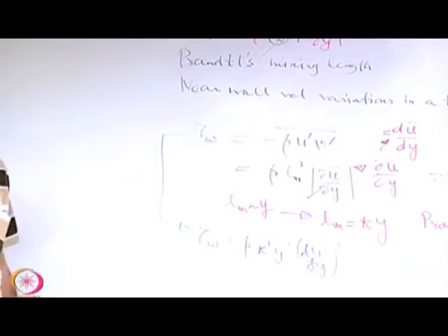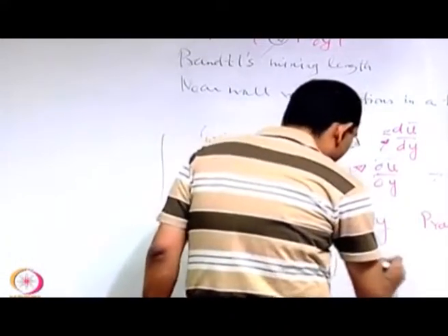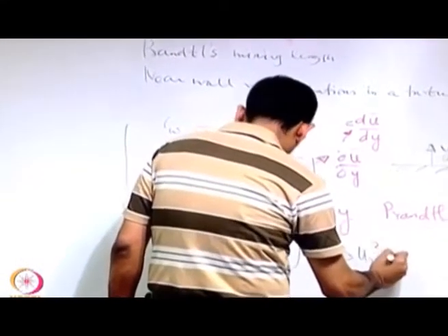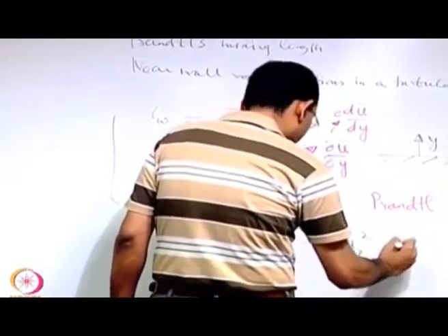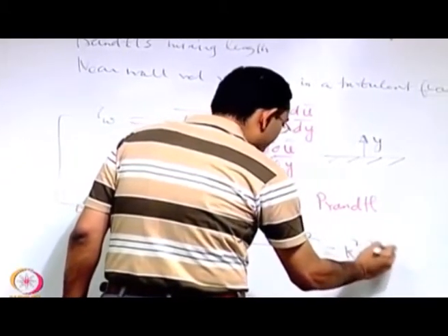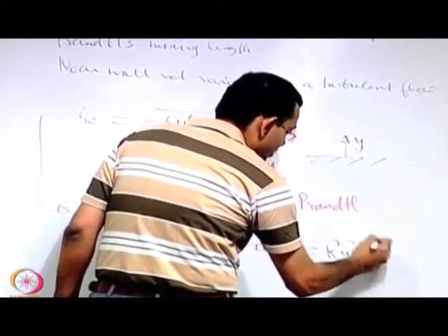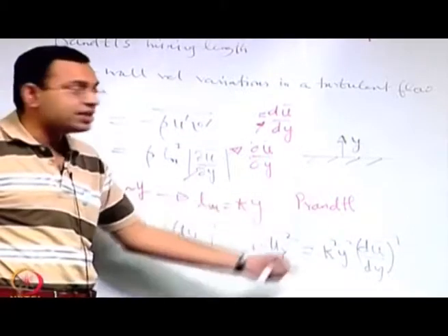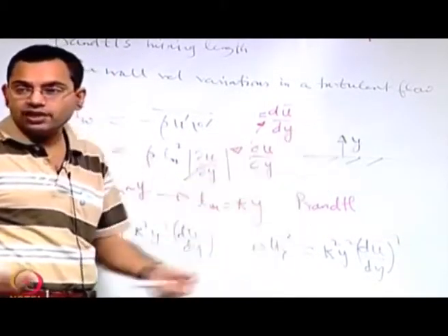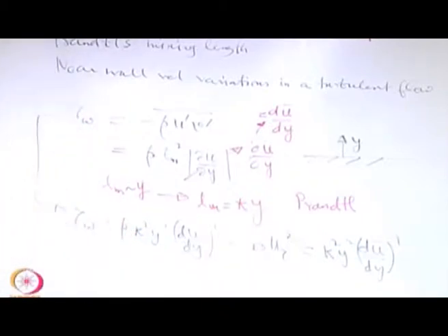What is the velocity scale, square of the velocity scale close to the wall. So that means you have u tau square is equal to k square y square (du/dy) square. Now you may extract the square root by referring to the proper sign by keeping this positive y axis in mind. So if you do that, you will get u tau is equal to k y du/dy.